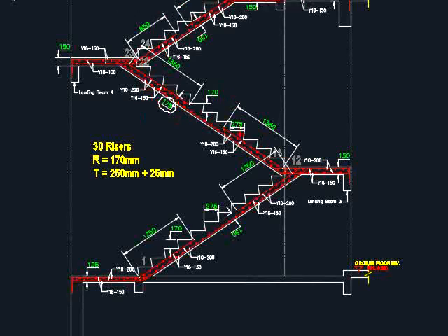In fact, you can actually standardize the thickness of the staircase throughout the entire building. That is dependent on your design, but on the basis of practicality, maybe you should just standardize it to become 175, meeting the requirements of the staircase of the longer span, so that none of the staircase here will fail.